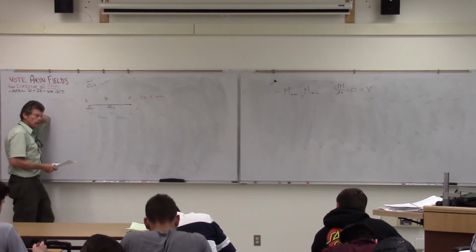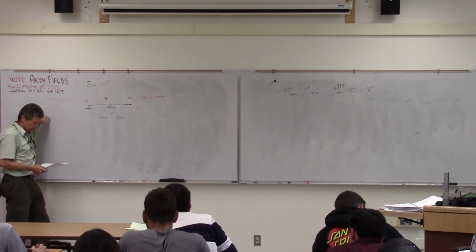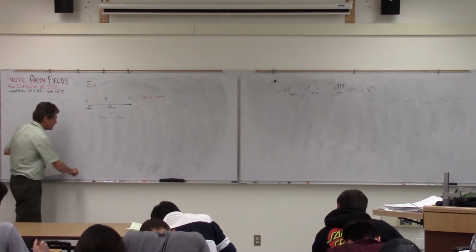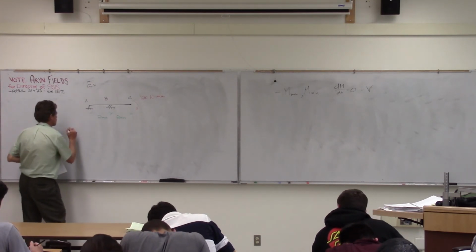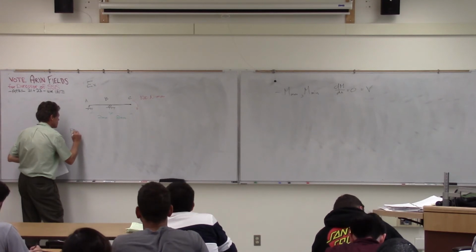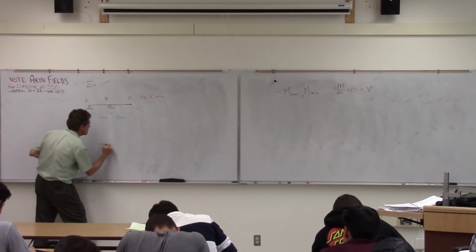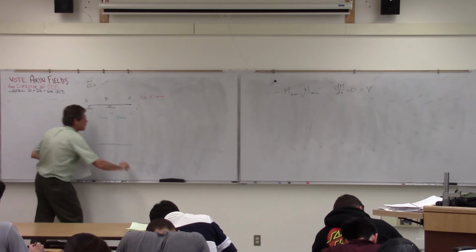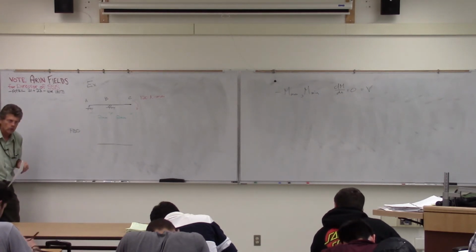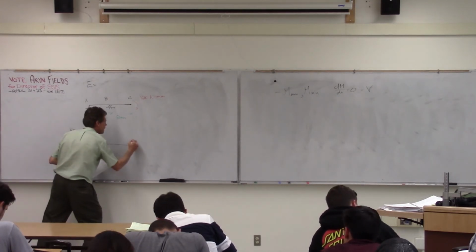Okay, so we've got a problem like this, and we're going to be asked to draw shear and moment diagrams for it. The key thing is then we want to think about that, and that's why I keep saying think about it in terms of its free body diagram. What we're going to now do is substitute what those support forces are providing.